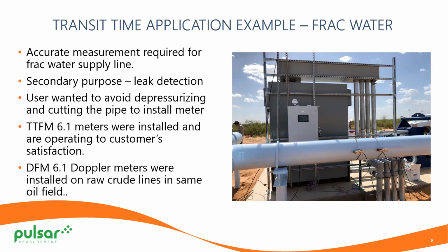And you'll see in this example, that's probably looks to me like about an 8 to 10 inch pipe. The transducer spacing is a little wider apart. The smaller the pipe gets, the closer those transducers tend to move together. But that's all predetermined by entering information into the control box. And I'll show you a photo of that. And then after that, all you have to do is space the transducers accordingly. I hope that answered your question.